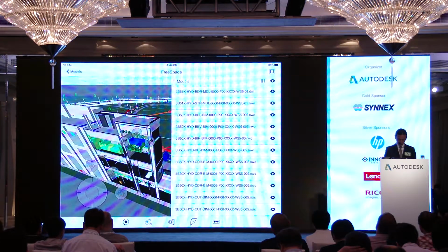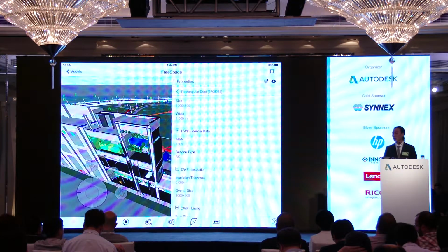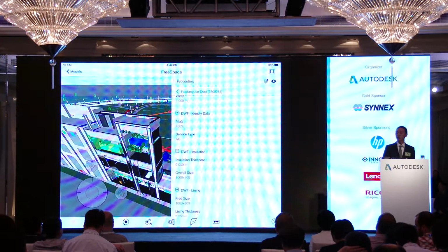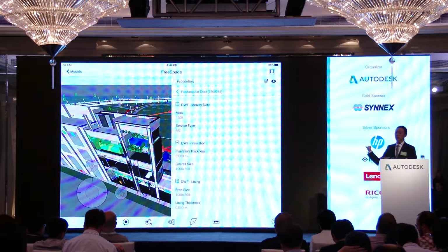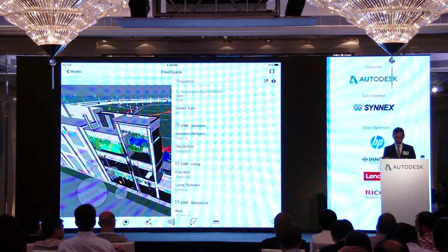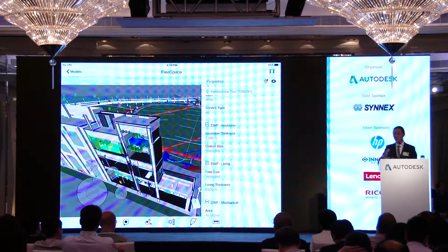If I press this and press the I, it's the same data as the parameters that you have put in. So whatever data you need, input into Revit, you can see the same data here. It's up to you guys what you want to see. Like if it's underground, you might want to see cover level and invert level only. And we will insert that in because it's Civil 3D, so it's already there.